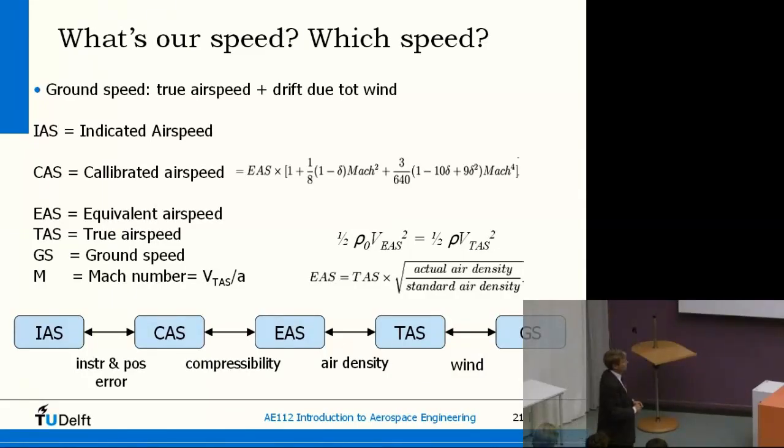You add the wind factor to the airspeed. So these are all the different speeds. If you see the character V for speed in a formula, that is normally the true airspeed. If you look at pilot manuals or Wikipedia performance data, it's always the equivalent airspeed when the speed is expressed in words.